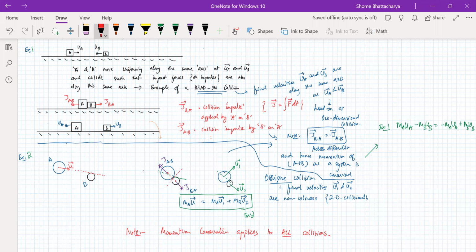Sir, so impulse will be from center to center, na? Yes. We are assuming it's like two discs, like on a carom board. So when they come in contact, what type of force acts? It's a normal type of force, normal reaction type of force. Because of the geometrical condition, when two cylinders come in contact, what is the plane of contact? It is the common tangent plane. So the force that will act will be perpendicular to the tangent plane. It will be a normal force, so it will be along the center to center line. Understood why it's along the center to center line? Yes, sir.